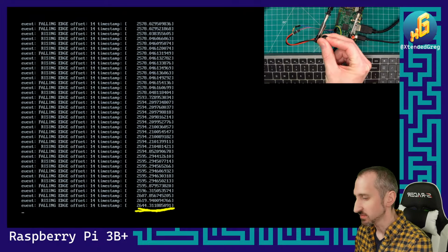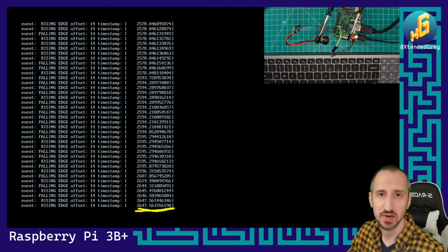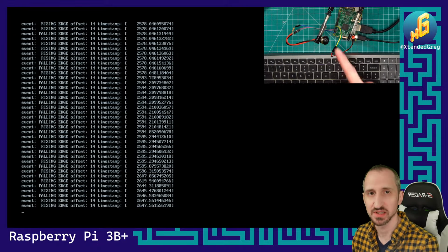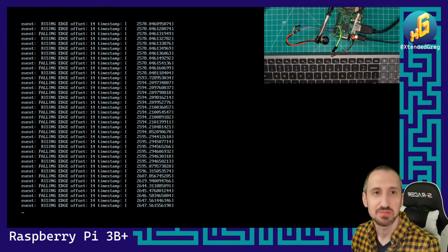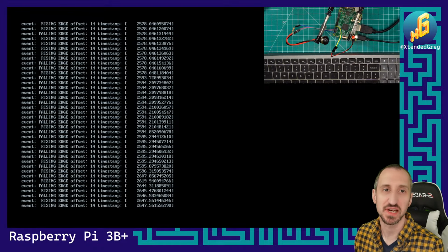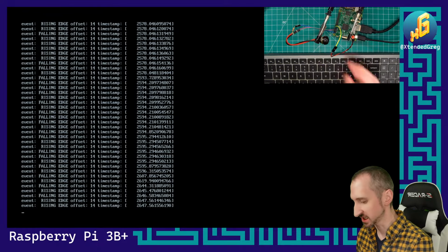So if we have a long delay between presses, we can see how long it has been since the last time we pressed the button. Something definitely to keep in mind with physical buttons especially is that when it makes contact, it may bounce the connections, and the computer is fast enough that it will potentially read all of those button presses.